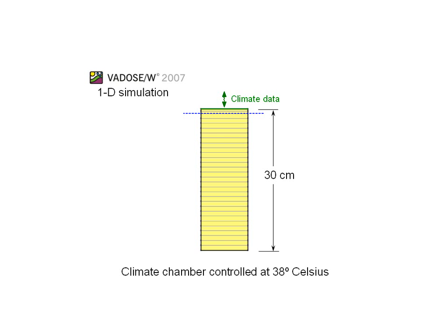The initial temperature of the soil profile will be specified as a material activation property of 38 degrees, and a water table will be used to specify initial pressures in the column. The model will be run for 40 days of climate data, where the climate data represents the potential evaporation, temperature, and relative humidity that was measured and monitored within the controlled climate chamber.